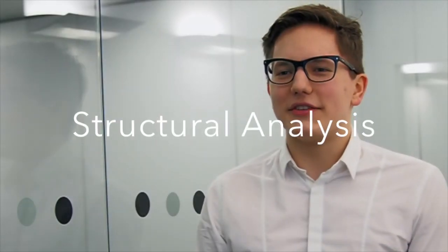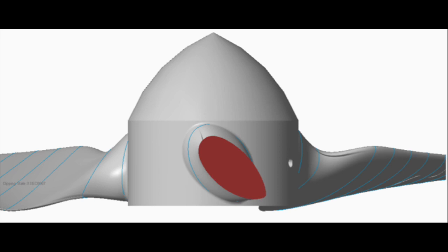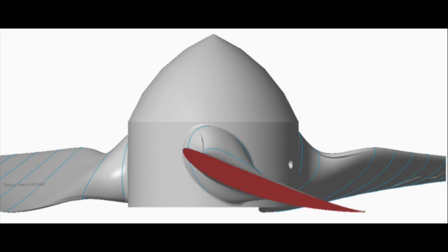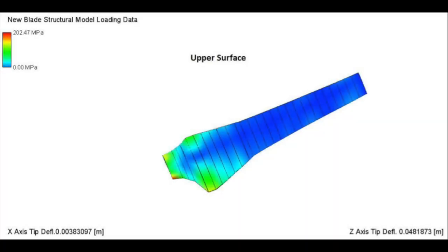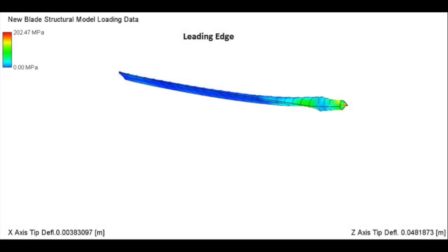The key idea behind the structural design was to create a structure that will be as light as possible as well as have an optimal aerodynamic performance. While making the structure lighter, we aimed to make sure that the critical stress in the ABS plastic was not reached at any point. We also made sure that by allowing certain stresses, we did not get excessive deflections, as they may have adversely affected the original design configuration of the blades and therefore impacted the performance of the turbine.